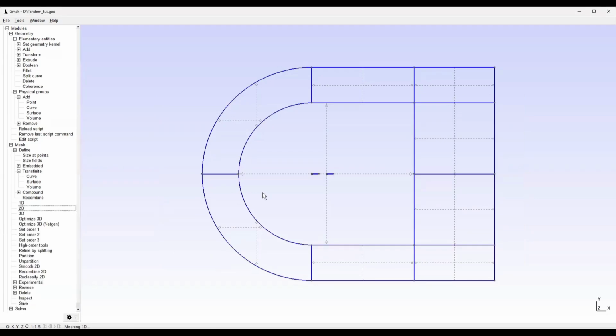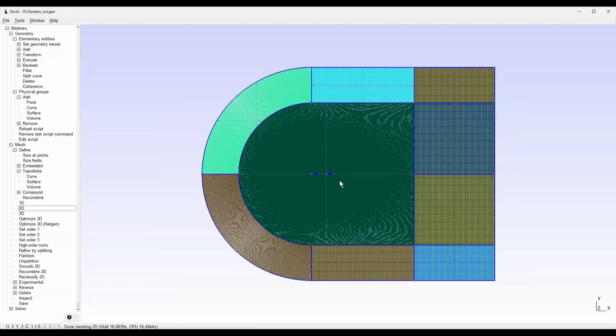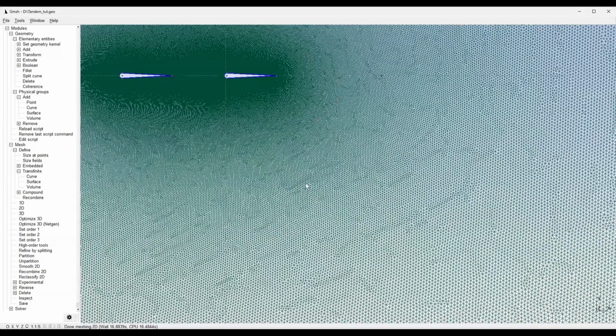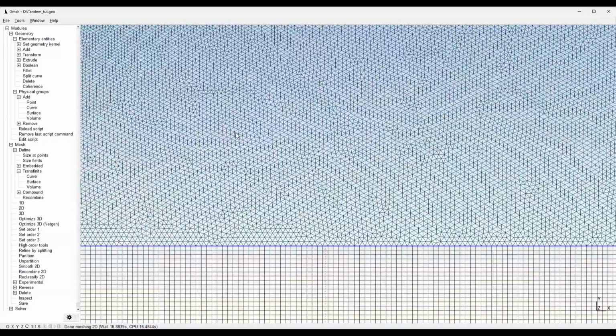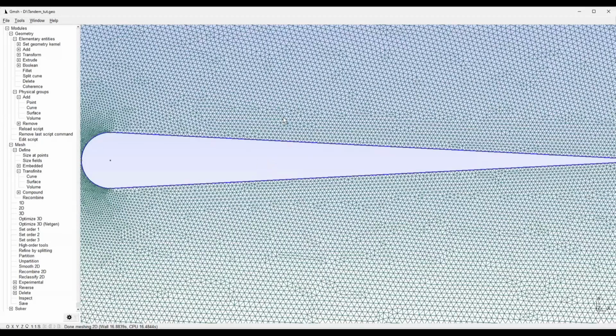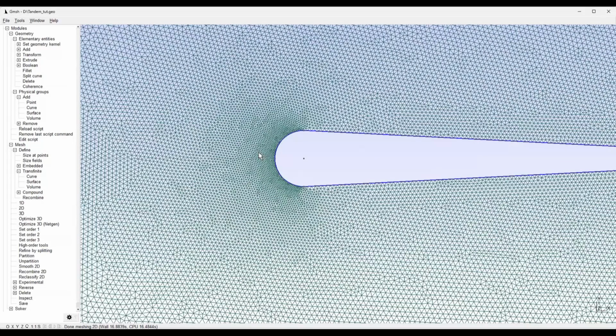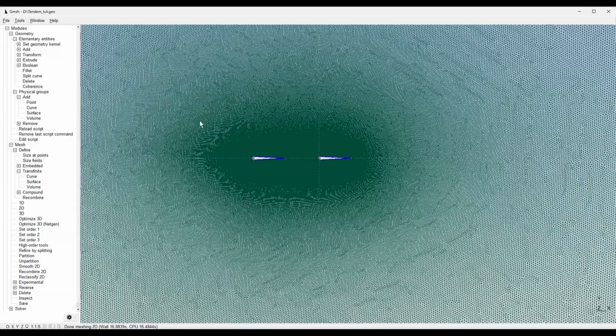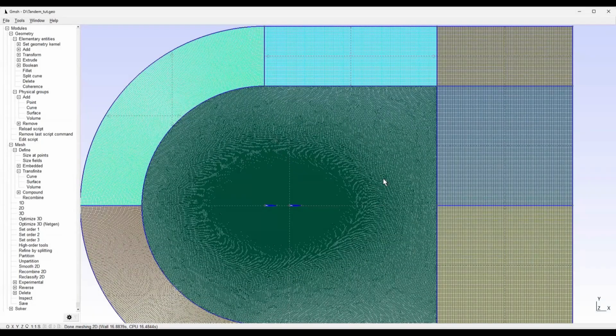Like that mesh. Yeah, so that's all good. We need that. So yeah, it's making it, just remove the recombine there, make it more triangular. A really, really nice mesh now. Got that nice mesh around there. So yeah, really, really nice. You just need to name these surfaces and you can put it into